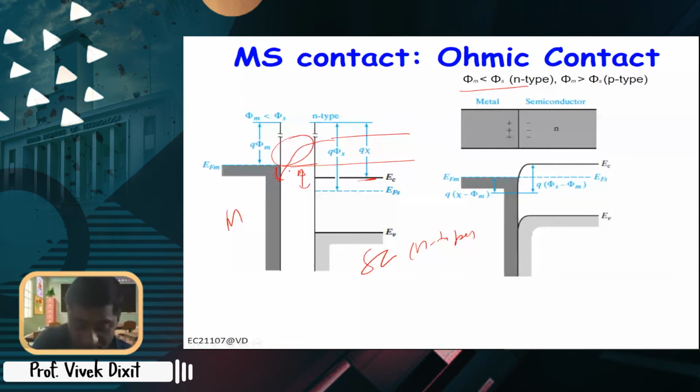And you notice one more thing here. This Fermi level is higher, so it will have the tendency to supply the electrons, right? And you notice the gap, right? This region becomes the conduction band edge close to the Fermi level. So here there is an accumulation of which type of carriers? Electrons, right? So there is no depletion region here. Charge is provided by the majority carriers, and there is no depletion, or you can say there is accumulation.